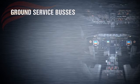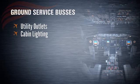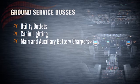When the AC ground service buses are powered, the following items are available: utility outlets, cabin lighting, and main and auxiliary battery chargers. Note that DC power demanding components are unavailable. To override the ground service configuration, both AC buses must be powered by some other source of power.